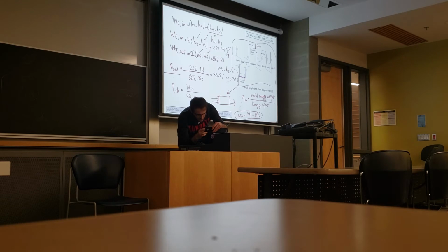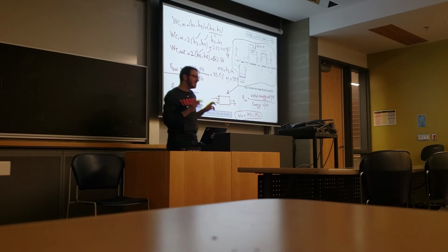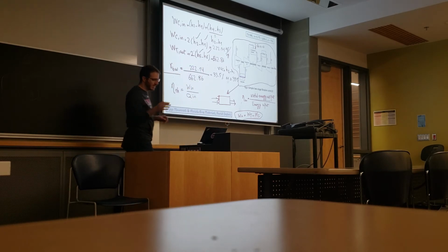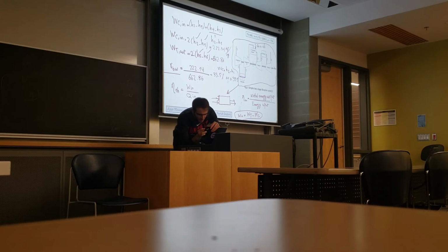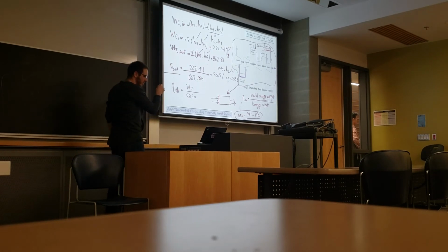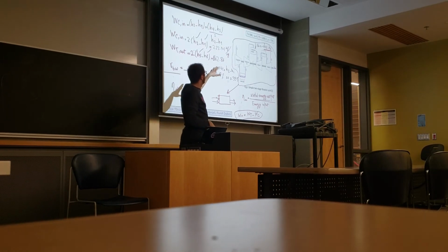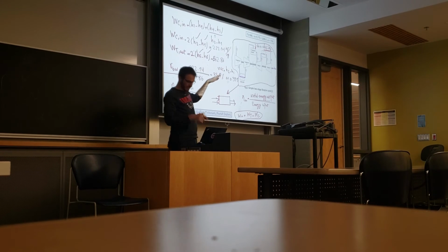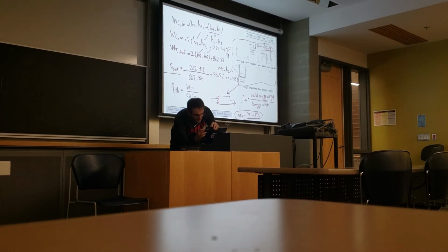So basically the very simplified form of Qin can be written as H5 minus H6, okay? But it's not the case in real, so the equation can't be that simple. But in your case, just write H5 minus H6, and for the reheat, also H7 minus H6.